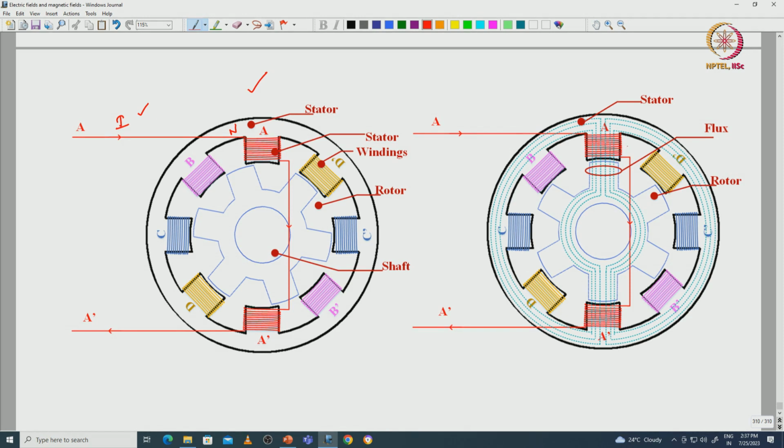If we excite A, automatically based upon the reluctance, the rotor will try to align with respect to the A phase winding, that we can see in this figure. Or in other words, similar to the electromagnet, this iron pole, that is rotor side, we have iron poles, there is no winding, that is the advantage with respect to the switched reluctance machine. So, the nearest pole near to the excited stator winding will attract. Okay. So, based upon the reluctance also, it will move towards the excited winding.